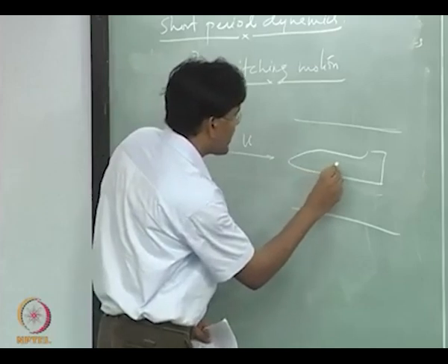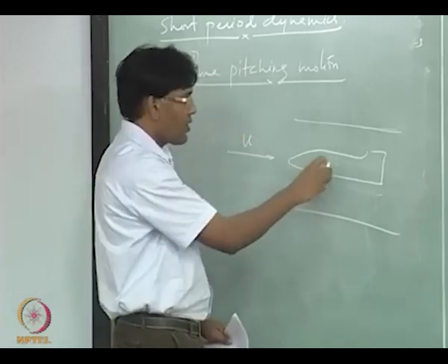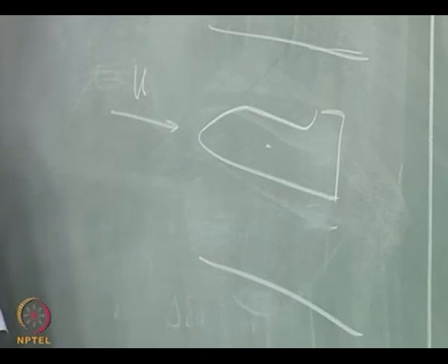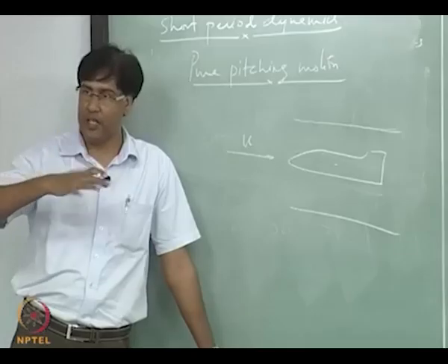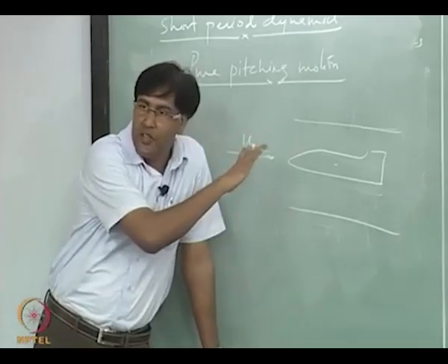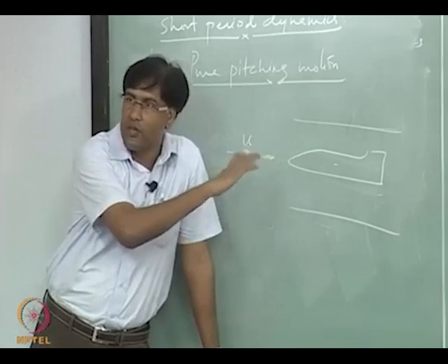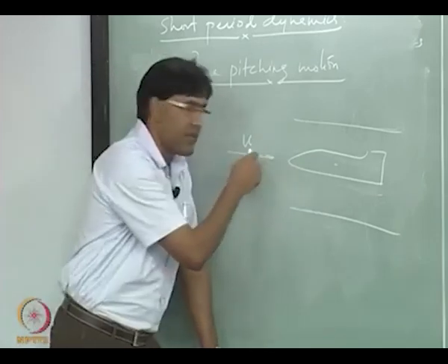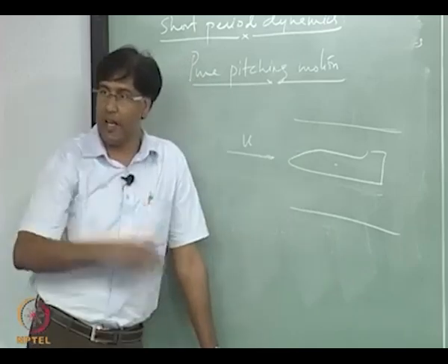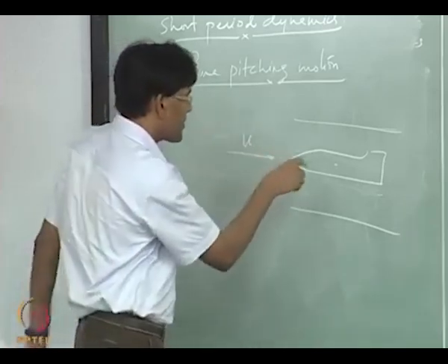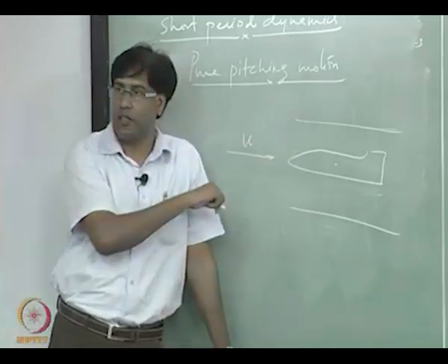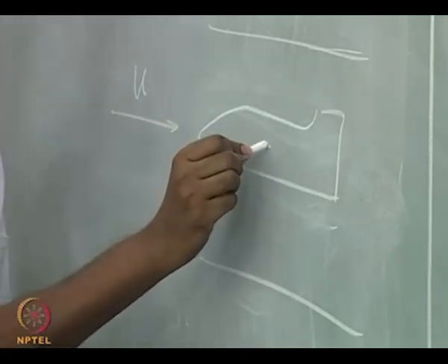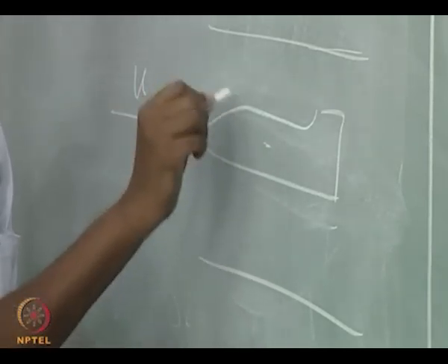So, you have motion around this point through which we have passed the rod in the wind tunnel. So, aircraft will start pitching about this. It is actually constrained to only have pitching motion and nothing else. So, you cannot have a forward speed or any other motion. So, only pure pitching motion is possible in the wind tunnel, right, if you pass a rod through this point. Okay.